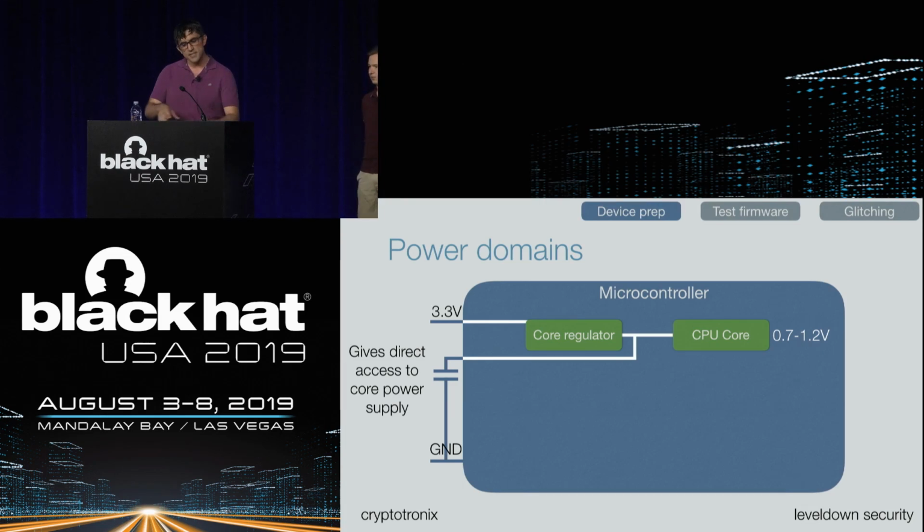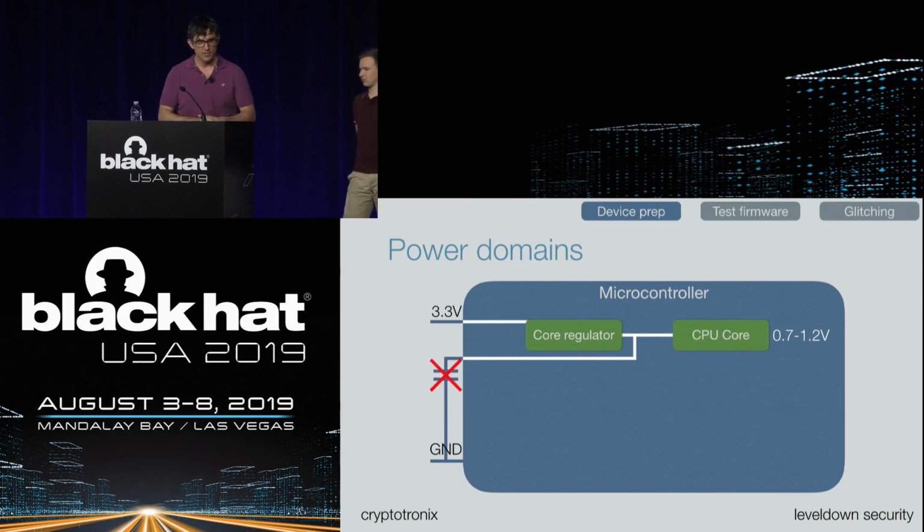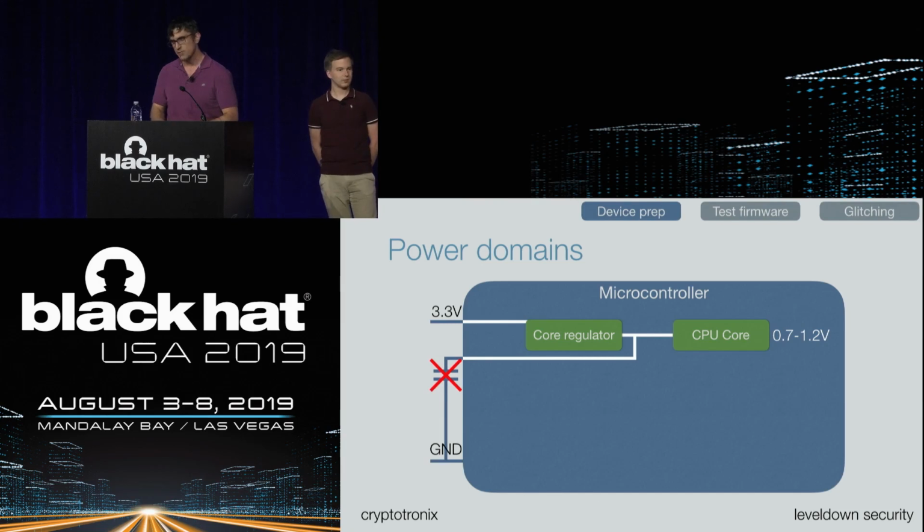What's nice about this block diagram is that that logic pin that's coming out external to a capacitor, bypasses this core regulator. And so what's really nice is when we remove that capacitor, take it out of place, we can potentially access that voltage to that logic core directly. And so that's going to be very useful for us later on.